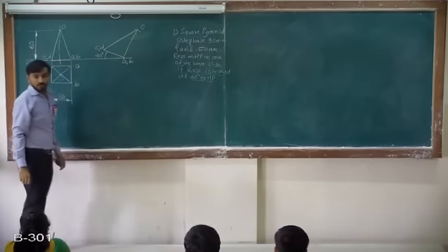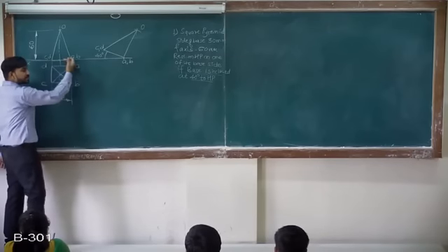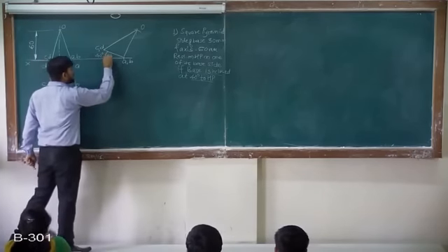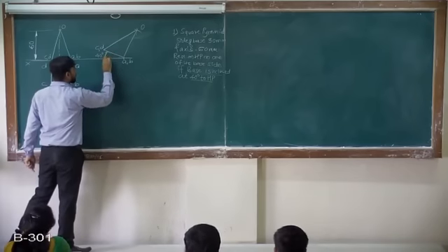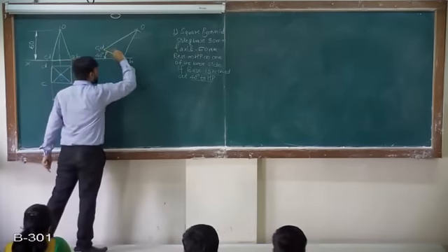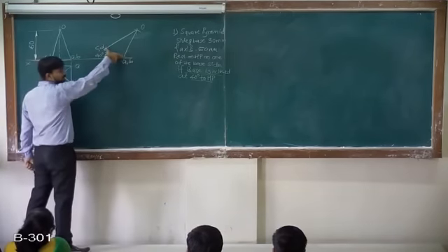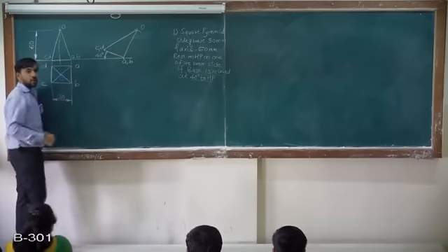This is O. So the second condition was the angle made by base ABCD. I have taken this base angle as 40 degree with respect to HP. I have drawn this line 40. I have marked this ABCD distance AB to CD here. Then I located the O point.